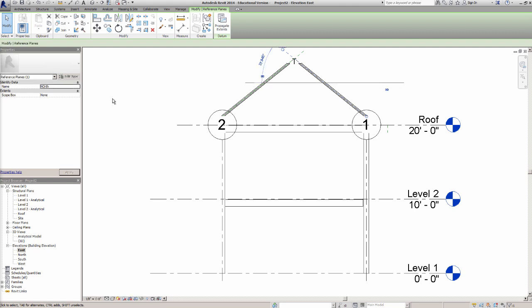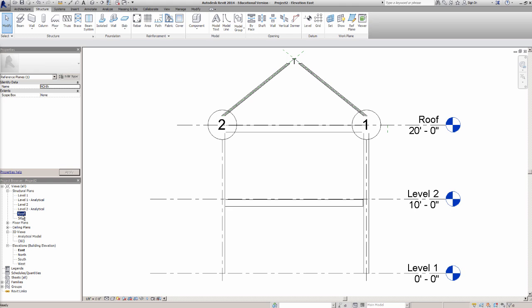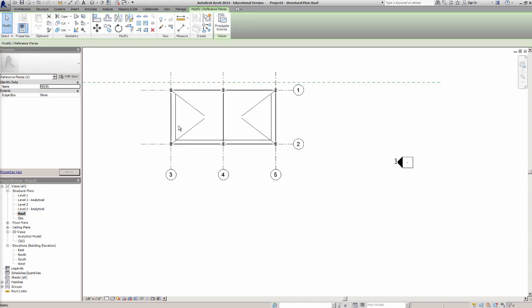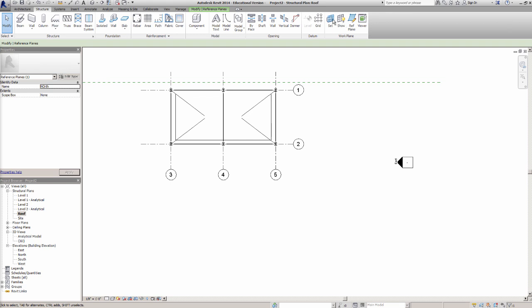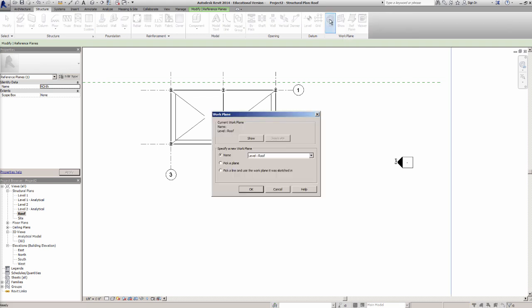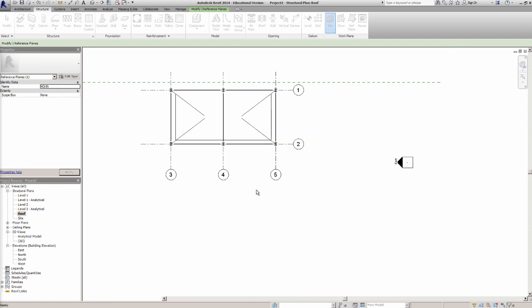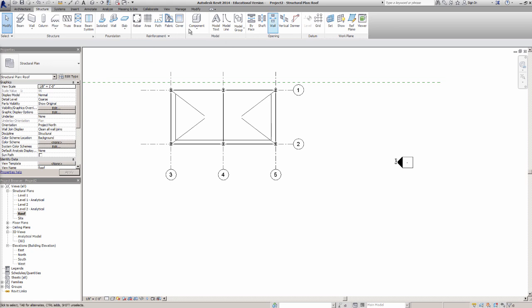So those are our roofs, and the work plane is no longer horizontal but aligns with the direction of the roof. So in order to then put the beam system in, we can go back to our roof line. And so from our roof view here, if you go to your structure, we're going to now set the reference plane no longer as roof, but we're going to look now and we should have the north and the south. So we'll do the north first, hit OK, and I will go ahead and put in a beam system.